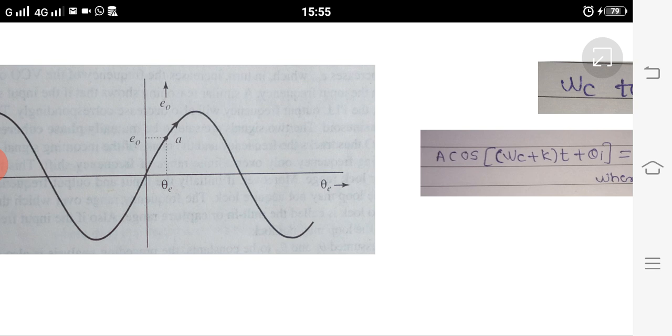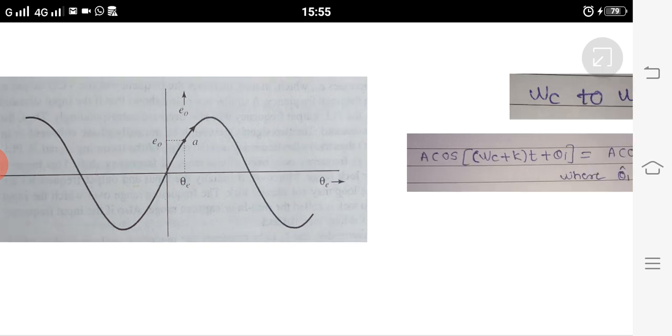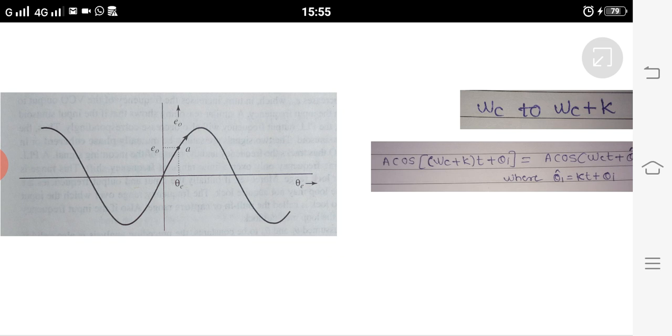The PLL can track the incoming frequency only over a finite range of frequency shift. This range is called the hold-in or lock range. Moreover, if initially the input and output frequencies are not close enough, the loop may not acquire lock. Therefore, the frequency range over which the input will cause the loop to lock is called the pull-in or capture range.